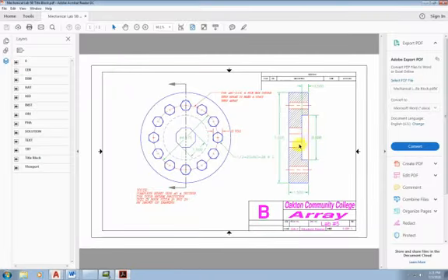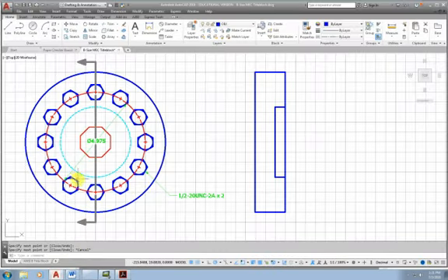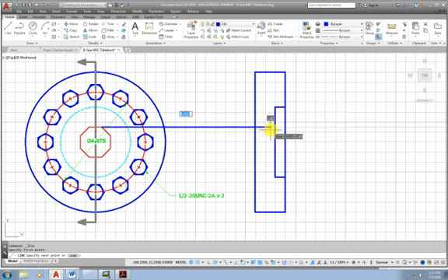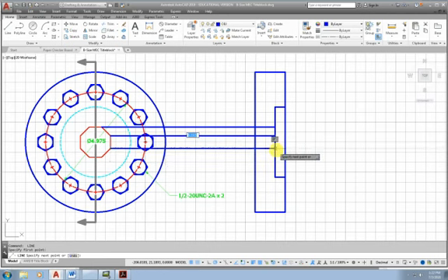Alright, I'm going to do the same thing for these lines here. They're going to translate to the corners, and this is what's known as orthographic projection. In other words, we want to project our object lines from one view to the other. Everything should line up, and that's how we get what they would call a glass box, where the part was put in a box and then we'd be looking at it from the side view. I'm going to bring these back.